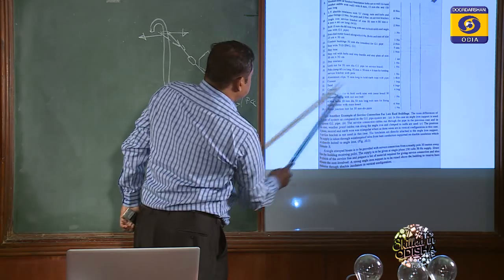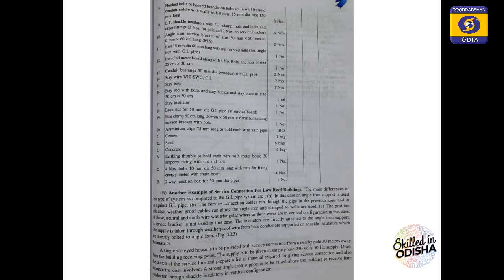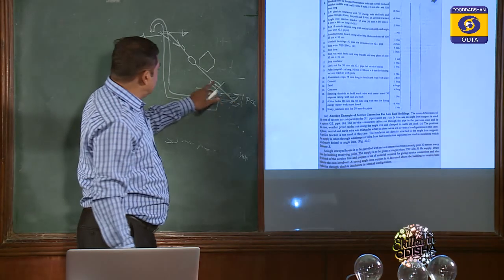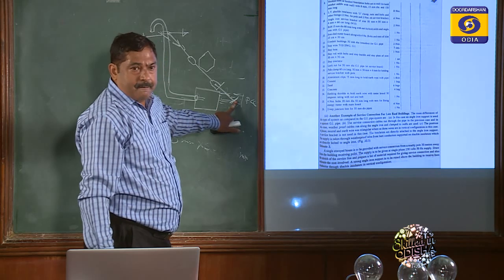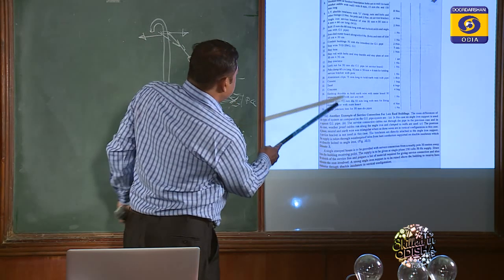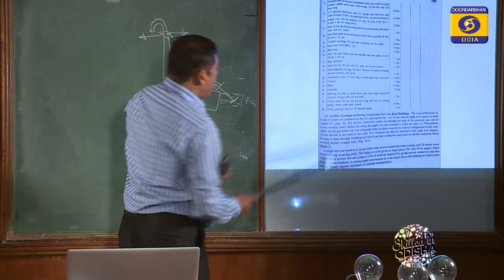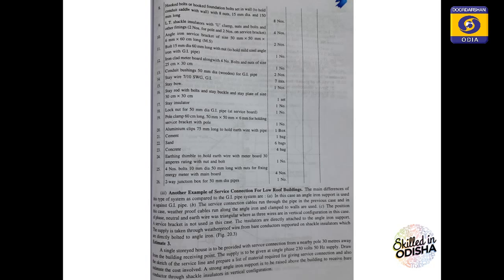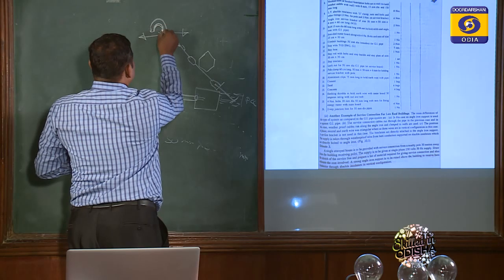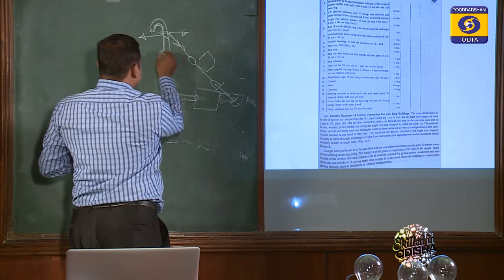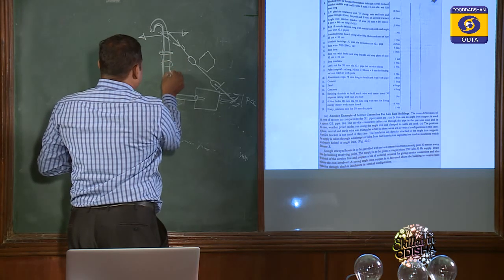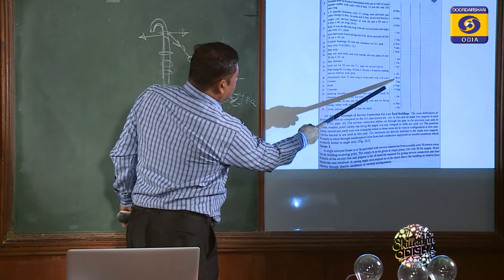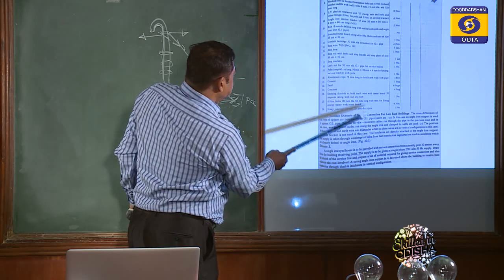That is why we need cement, sand 6 bags and concrete 4 bags. These things are only for fixing this particular stay rod. And we give small aluminum clips to hold the GI wire, the earth wire, which goes here. These earth wires also have to be connected, so we give aluminum clips also. One packet will do. So aluminum clips, one box.